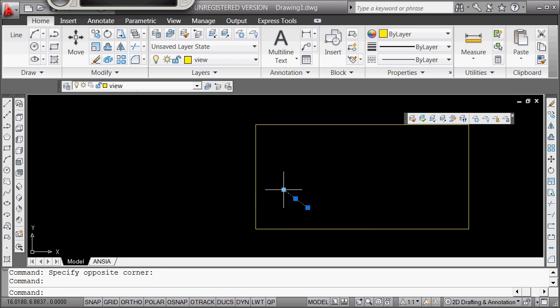I'm going to left click, spacebar, spacebar, C for copy, rotation angle. I'm going to put my hand down and decide whether it's positive or negative. I'm going to say 85 degrees because my thumb is coming out of the page, and then I'm going to hit return here. I can now type L-E-N.